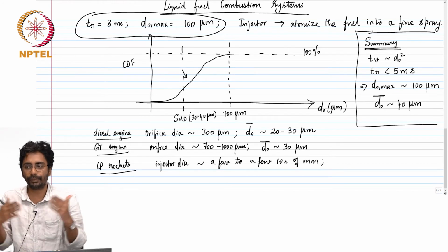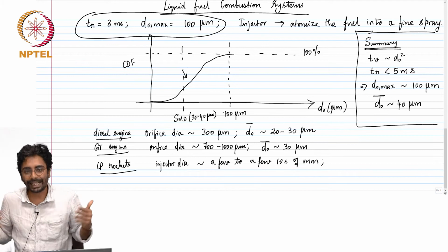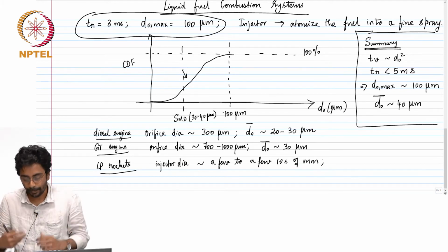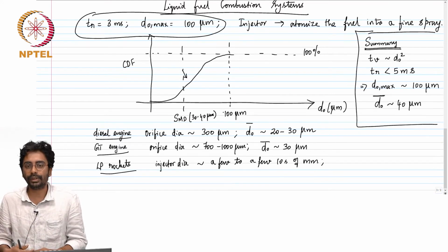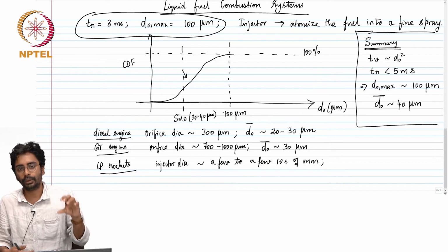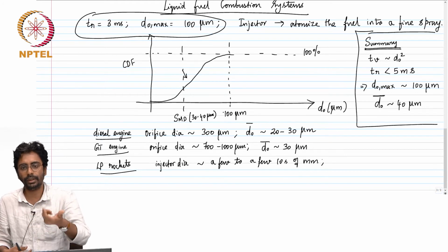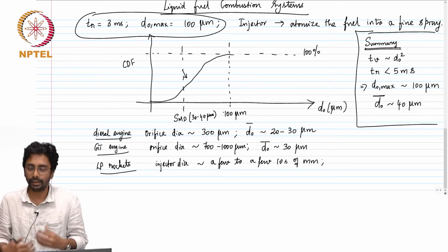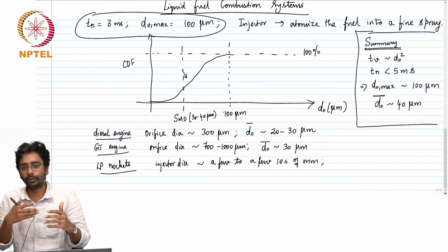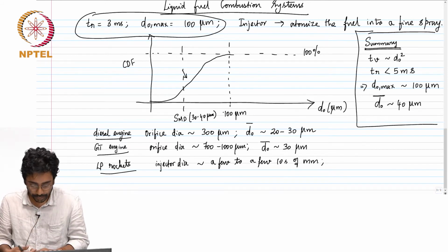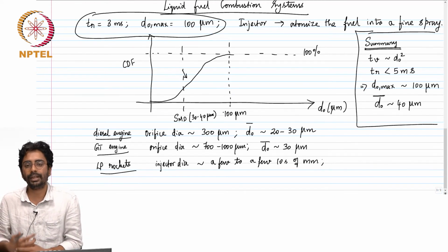It's either impinging jets. If you have both oxidizer and fuels in liquid form, you create jets and make them impinge, and the process of impingement breaks the jets into finer droplets. That's called impinging injectors. The other type of injector is called a coaxial injector, where you have coaxially flowing jets, one component is gaseous, usually the fuel is gaseous, the oxidizer is liquid. In the cryogenic system, for example, the semi-cryogenic system, the fuel is liquid, the oxidizer is gas, and therefore the shear between the coaxially flowing jets breaks the fuel or the oxidizer, depending on which system you are looking at,